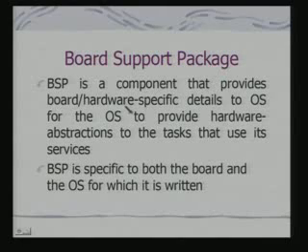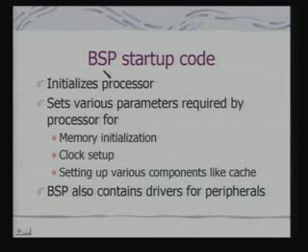BSP is a component that provides board or hardware specific details to the OS for the OS to provide hardware abstractions to the tasks that use its services. And BSP is specific to both the board and the OS for which it is being written. In fact, this can be configured also for the board for which it is being written. And what it does is provide board and hardware specific details to the operating system.